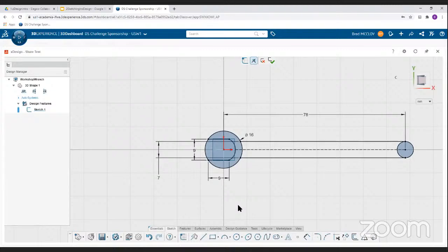It's looking a lot more wrench-like, but we've got a blue colored circle here, a blue colored circle here. So the problem is they're two independent solids right now. What we want to do is maybe cut some of the lines away to make them flow into each other, to let the package know that this is one piece. So down here we get this little scissor tool, which is trim or extend. So we click that. You can see now we've got a little scissors. What we can do is start to draw a line. If we trim that, we can come down and trim this.